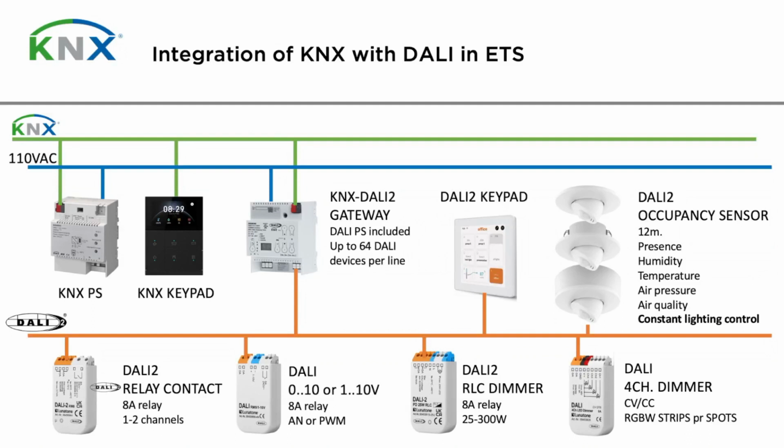If I lose communication with the ECG, that means the DALI is not working, or that ECG is not working. If I get an error from the ECG, I just need to read the manual and see what the error is. Maybe it's overload, or line out, or whatever. But yes, I do have feedback. This is the powerful thing.